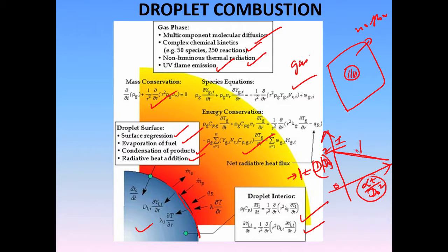This linearity of the profile suggests that with time there is a constant slope. So, this means that d by d naught square will be some kind of a constant slope kt, no matter how you normalize time. The slope value can vary depending on what droplet you are dealing with, but they got a constant slope no matter which droplet they dealt with. So, this was proposed in the famous d square law by Law and Sirignano.